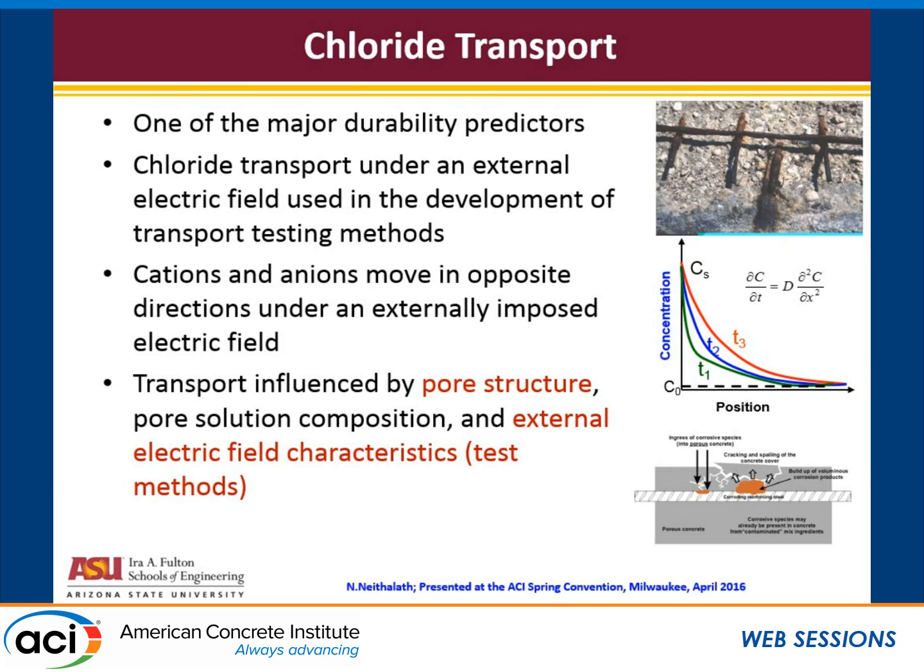Anytime you do a resistivity test in a saturated solution full of hydroxide ions, you're pretty much picking up the hydroxide ion effect predominantly. So that is something to be considered rather than just looking at those numbers. I'll show you a few ways to tackle that too.